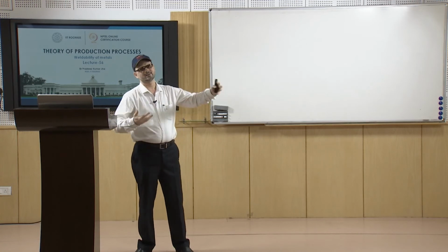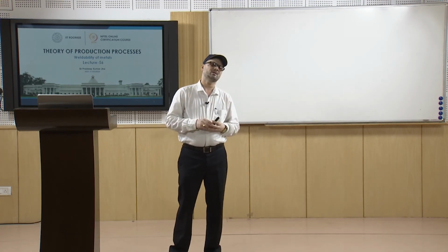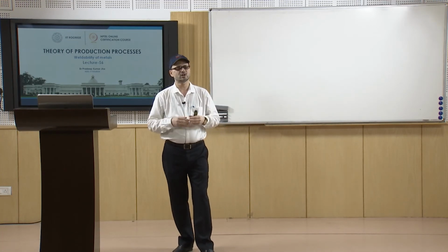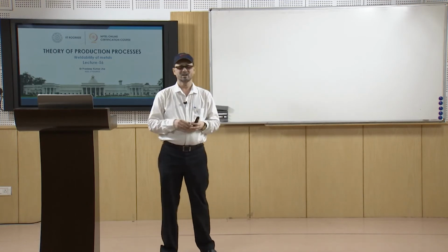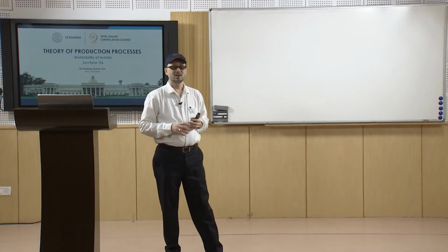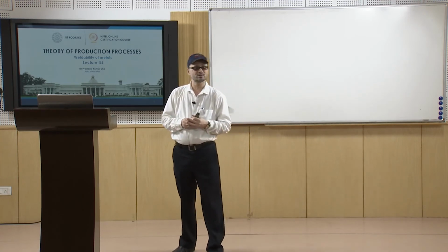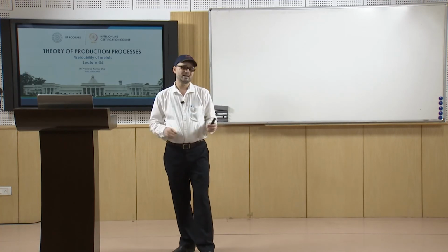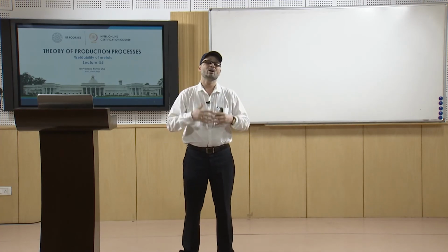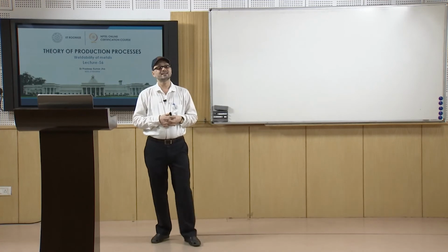Like you are trying to weld a material which has, suppose, composites, or even aluminum alloys. Now, let us say aluminum material first: aluminum based composites, aluminum alloys. The basic challenge with aluminum alloys is that aluminum is a very fast conductor of heat, so you have to make a proper selection. You cannot do it with flame welding, because the heat extraction rate is quite high and the rate of heat input is very slow. Also it has a tendency to oxidize. But it does not mean that it is not weldable.